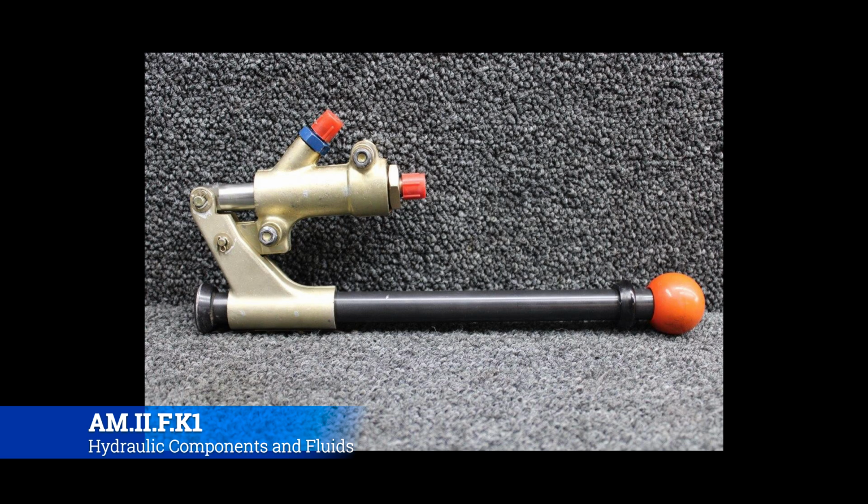Okay, so let's talk about different types of pumps that you can find on an aircraft hydraulic system, and we'll get into the role the pumps play here in just a minute. Whenever we actually start talking about the hydraulic system itself, we'll talk about the all-encompassing why do we have hydraulic pumps. This one is a hand pump from a Cessna 210. So if the engine and electrical hydraulic pump fails, you can pump the gear down.